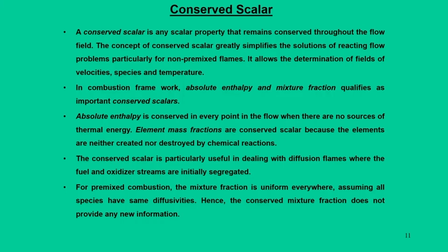If you look at a reaction globally, normally reactants vanish and products are formed, but what we can see is that when the reactant vanishes, there is some origin of certain fuel component that has traces throughout the reaction process. If you want to calculate particular information about that species, then a conserved scalar is a good approach, and two such important conserved scalars are absolute enthalpy and mixture fraction.